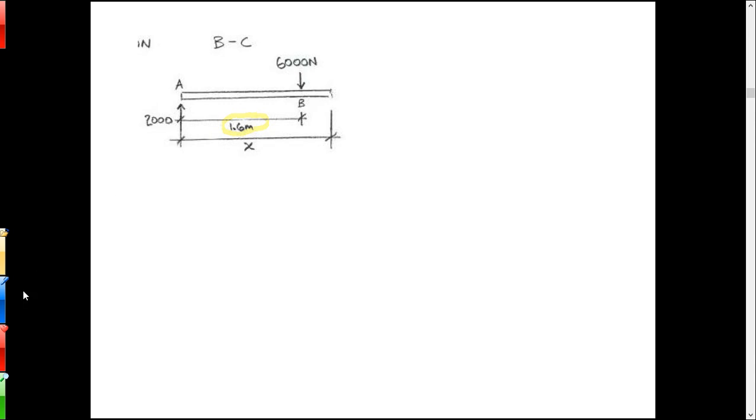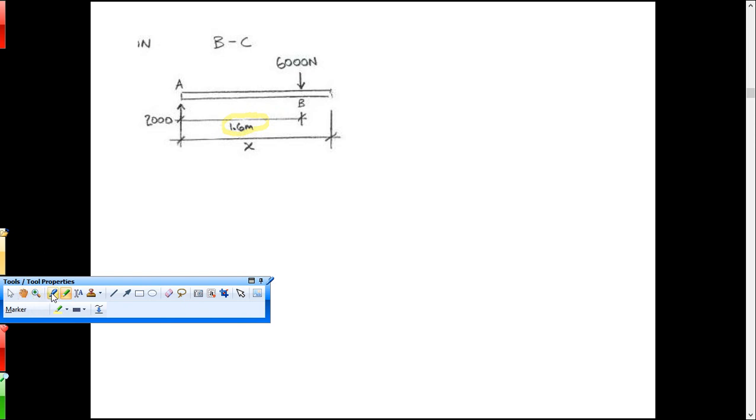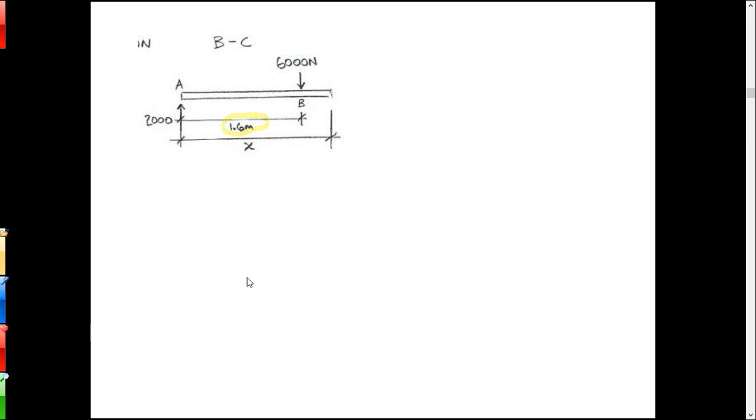All right, so I can add a couple little things to this. Let's put the shear and moment on there. On that end where I made the cut, that's where the shear and moment go. And really the things to remember about this is the shear goes down and the moment is counterclockwise positive. It curls the beam up. Okay, so there's the shear and moment.